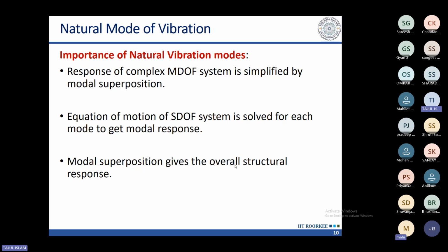You take any kind of software for any kind of structure. All the software uses the same concept. You do the modal analysis to simplify the structure, then apply the superposition method to get the final structural response. And this happens only when you do the response spectrum analysis. I'm not talking about the equivalent static method, because that itself is a single degree of freedom system concept. So this concept, multiple modal superposition method, is only when you are applying response spectrum method.